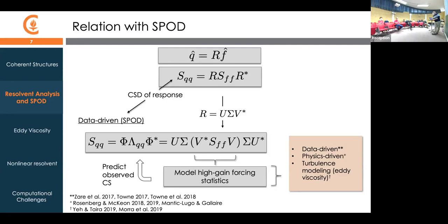But that's the advantage of doing this mapping, a macro flow mode. You're taking an SPOD mode and decomposing it into a U field and a V field. No, the SPOD modes are another basis for just the U's, right? It's a different basis, and in general they are different. It's the eddy viscosity model here that we've pushed to draw them closer to being the same thing. If they're the same thing, then the same forcing from the resolvent would be the thing that gave you the response.